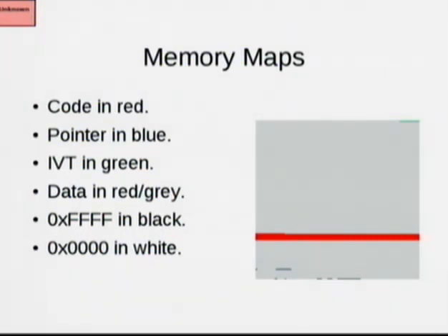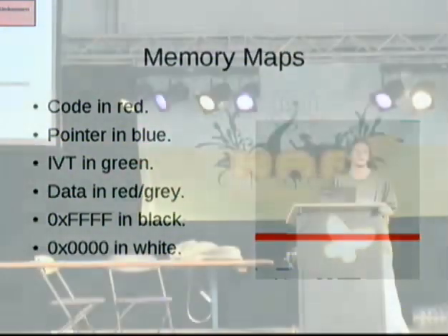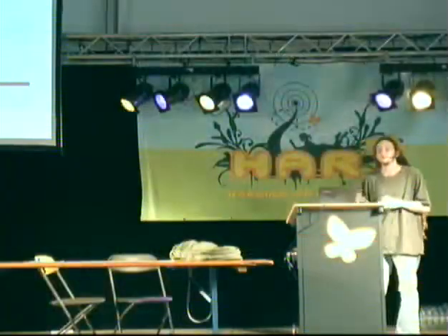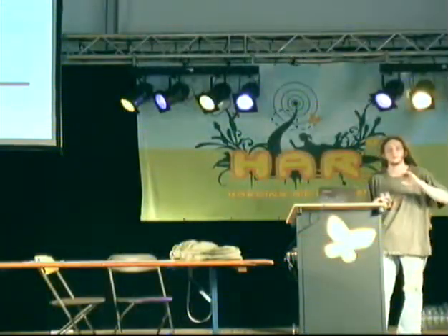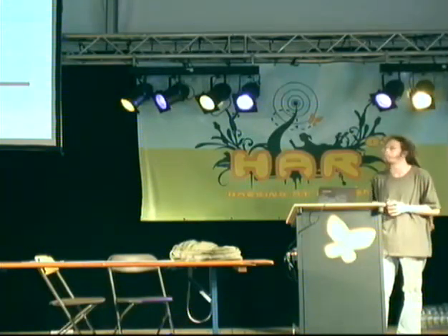And this allows you to distinguish between the two. You can also count upon the compiler placing them in particular regions. So in the case of GCC, executable code comes first in flash memory, followed by data. You'll also note that with many compilers, the data will immediately be copied to RAM as a bug. So if you find the same content in both RAM and ROM, you can be reasonably certain that it's data and not code.